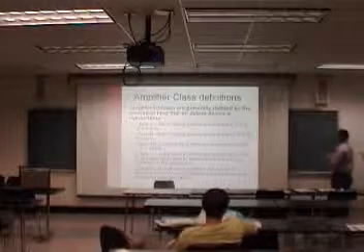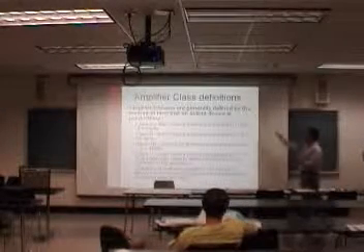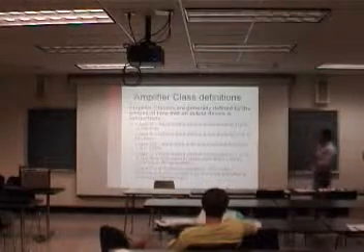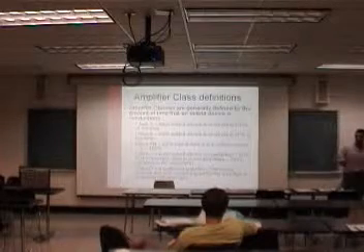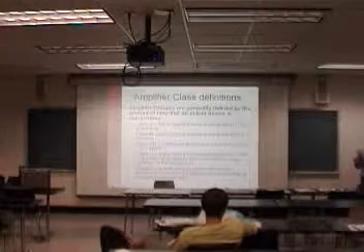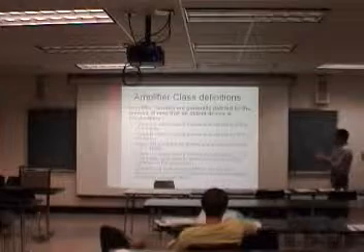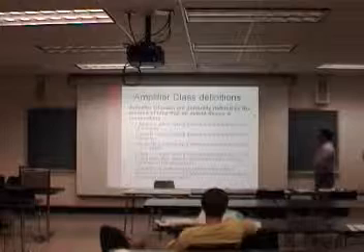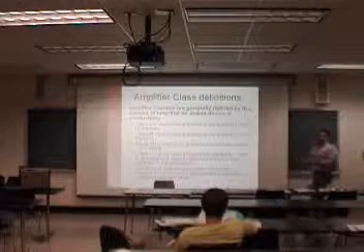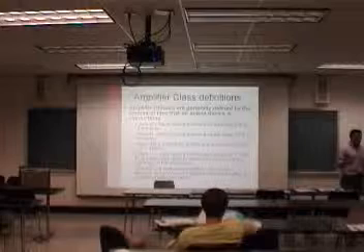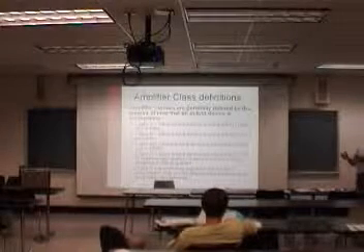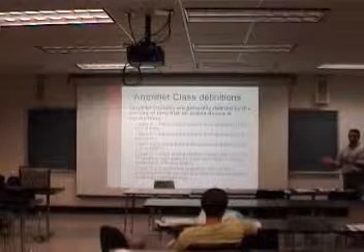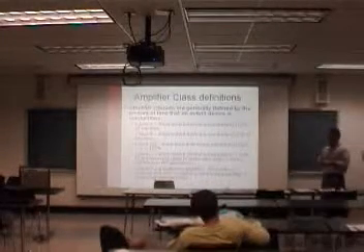Class D is an interesting scenario. It's totally different from the others, and it's a switching amplifier. What it actually relies on is something akin to sampling theory and reconstruction. I have a Simulink model that shows how it works, and I think that's probably a better way to illustrate the principles of Class D. So instead of showing a tube schematic or a transistor schematic, I did a Simulink model, and I'll show where things represent the tube or transistor.